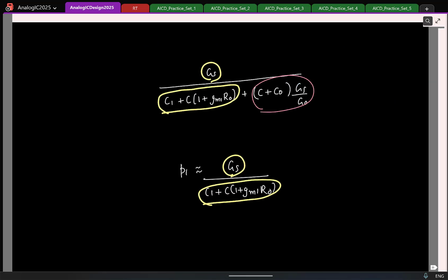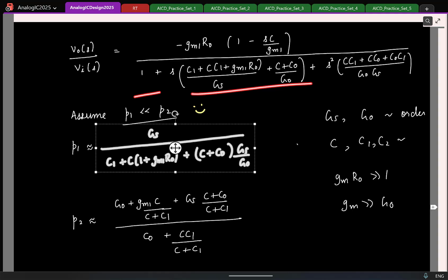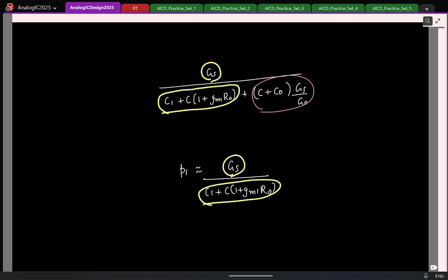And also to start with, we even solved the quadratic equation using an approximate result that I can take the ratio of polynomials. So you have done multiple levels of approximation, so all of them can be attributed to this additional term. But in practice, the dominant term is going to be this fellow, because I have a capacitor multiplied by a gain. That is going to be the dominant thing. So for all practical purposes, you can approximate the low frequency pole as this.